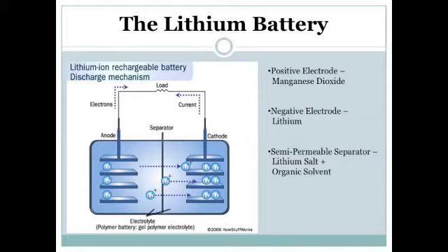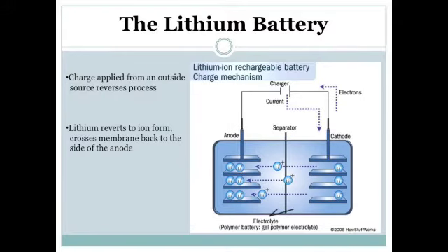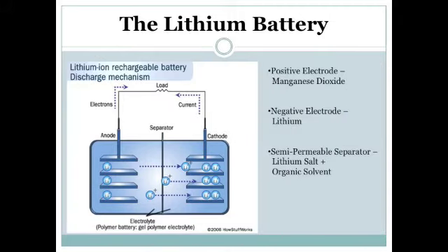When the battery is in use, ions of lithium move through the electrolyte from the anode to the cathode and deposit on the cathode. The electrons follow the same course along their own individual circuit. When the battery is recharged, the lithium ions move back to the anode by the application of an outside charge. The movement of lithium ions happens at a high voltage, 3.7 volts, as compared to a typical alkali battery which produces only 1.5 volts. This advantage allows for lithium-ion use in compact devices like cell phones.